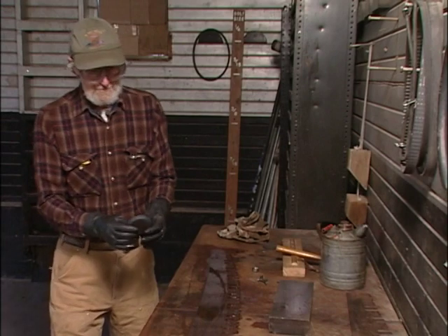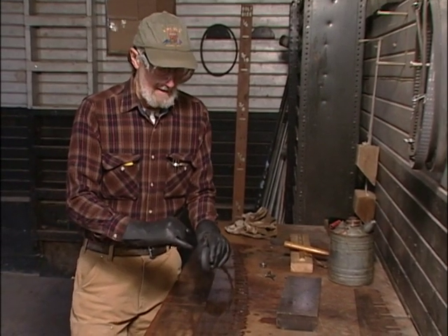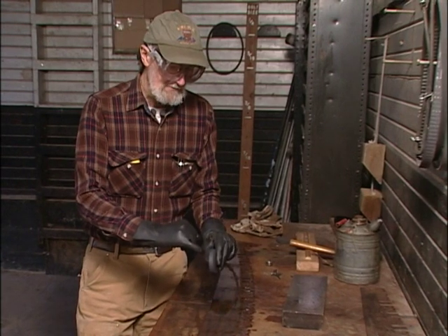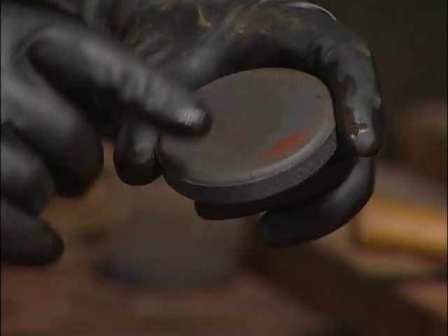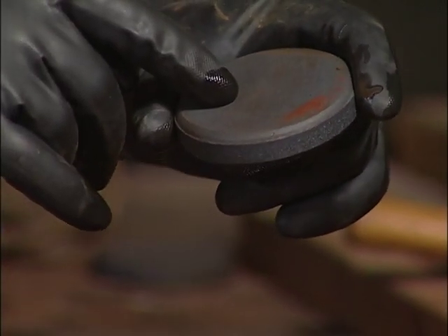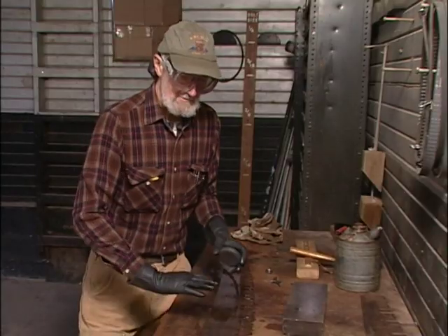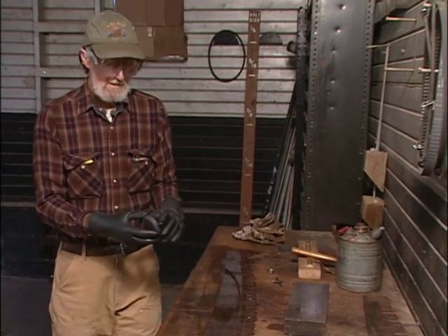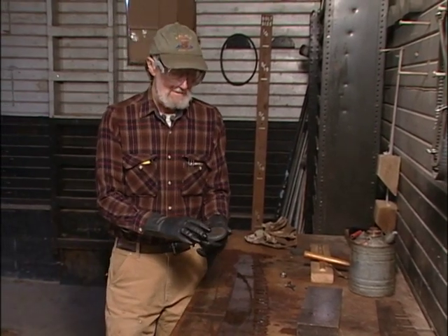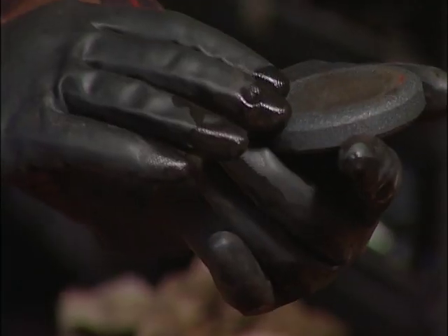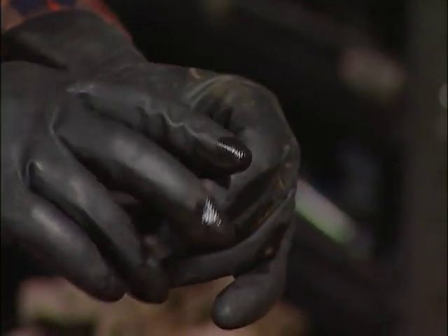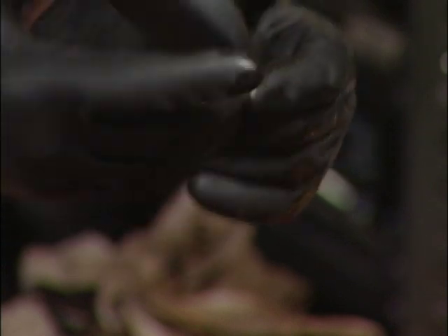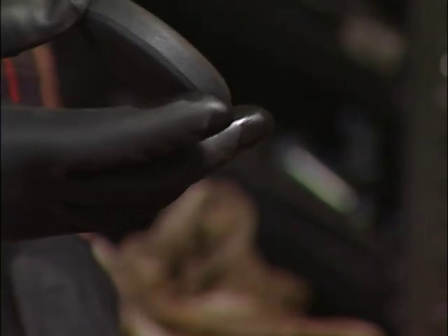These axe stones generally have two different grits on them. There's a coarse grit and a fine grit. I almost always use the fine grit just because there's less likelihood of scratching the saw. If I have a saw that has a lot of rust on it, it's a seriously rusty saw, I'll end up using the coarse side just for the initial work to clean the worst of it off, and then I'll use the fine grit.